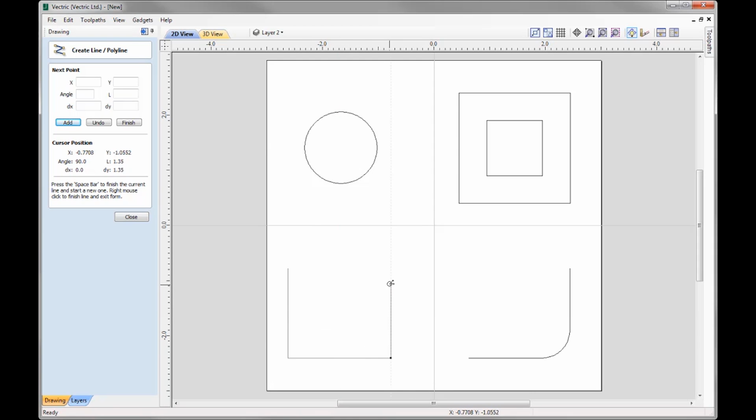And then I'm just going to go up, I'm going to align that to the top object bounds of the shape that I'm currently drawing. I'm going to click that in place. I can also do angled lines, so you can see I can follow along with those angled extensions, making it a lot easier for me to create accurate geometry there. So I'm just going to click that in place at the centre, so it's found the centre object bounds for the object that I'm currently drawing, which is handy, and then we'll just bring that down over here